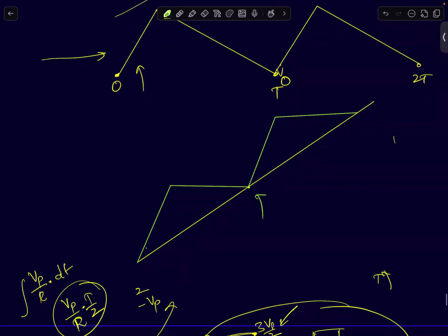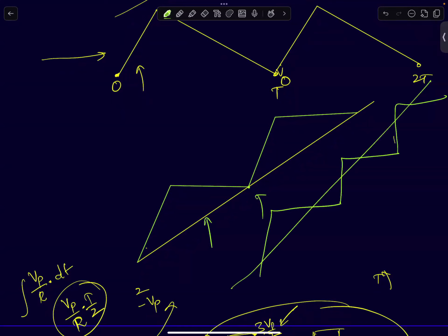It will be a waveform that is riding on top of a ramp signal. So your op-amp's output will keep increasing because of the presence of a DC signal. It will increase linearly like this. Eventually, it will saturate. After it saturates, the op-amp will go out of the linear operation mode, and the output will saturate to some constant value.